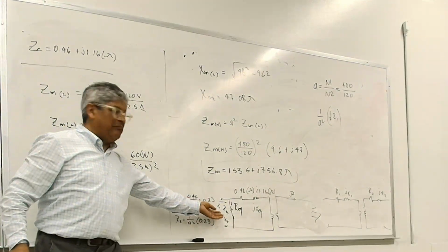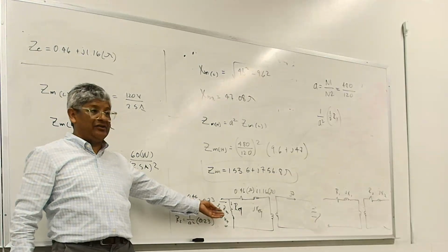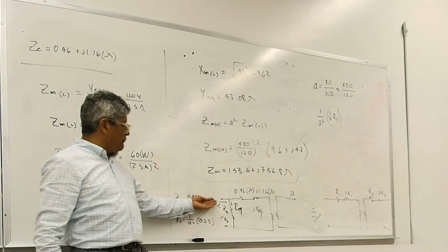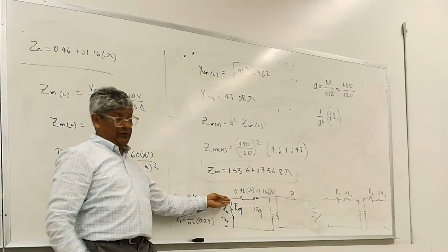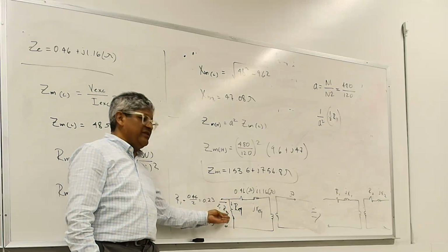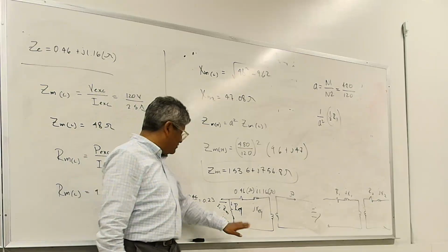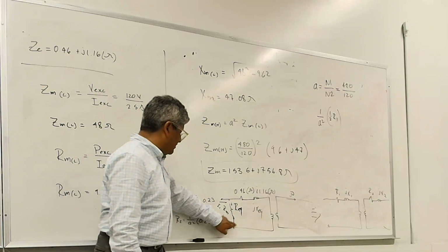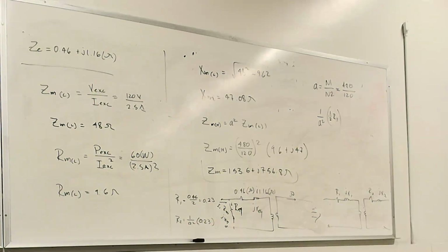So the better design you have, the higher that branch impedance, and the more current from the primary gets reflected to the secondary. Hopefully, if you did a really good design, very tiny amounts of current will flow through that magnetizing branch. That's why we tend to ignore it and say don't worry about it in analysis. But there are places where it is required.